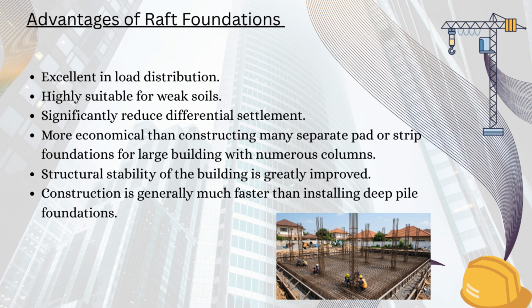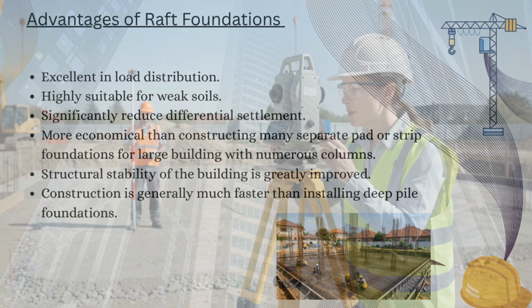Construction is generally much faster than installing deep pile foundations, since only one large excavation is required and no specialized piling equipment is needed. Another important advantage is that raft foundations provide excellent resistance against uplift pressures, making them particularly suitable for basement structures where groundwater pressure is present. Now let's briefly look at how a raft foundation is constructed.